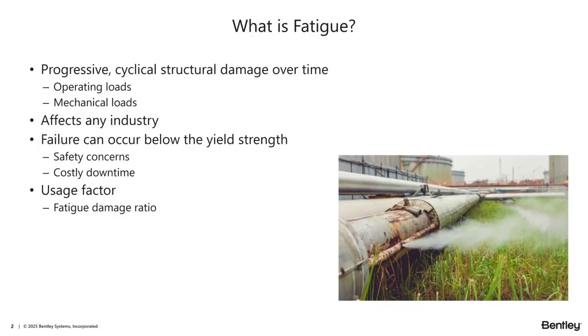So first off, let's begin by asking the question, what is fatigue and why do we care so much about it? Well, material fatigue specifically is an evaluation of progressive cyclical structural damage. Pipes are unfortunately not isotropic, as tiny defects that we call voids are introduced into the lattice structure of the material of the pipe during the formation process. As stresses are loaded and unloaded over time, these microscopic voids will enlarge and coalesce with neighboring voids, and these voids eventually reach a critical size that, while still being microscopic, can cause the whole material to fail suddenly.